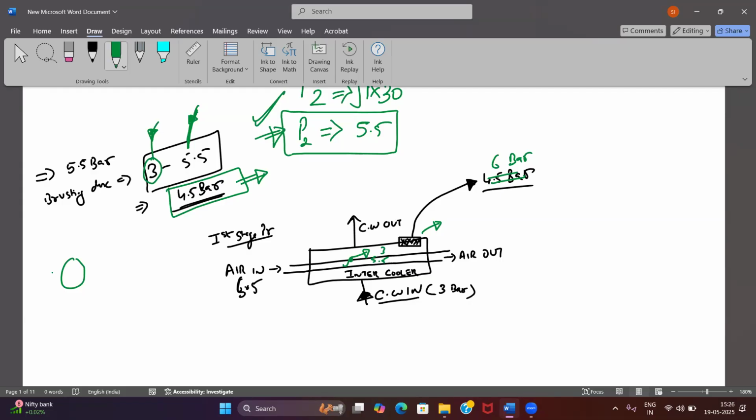So they have already tested that this material is going to burst at so and so pressure. You have to tell the manufacturers like this is my inlet pressure, this is my first stage discharge pressure, and this is my water pressure on board the system. Please supply accordingly, and he will choose somewhere in between. Is it clear? Excuse me, sir.